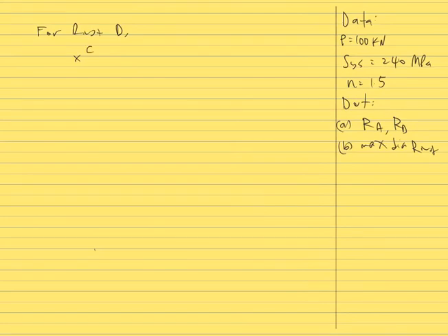So this is our centroid, and then this is our rivet D. So distance between centroid and rivet D is 90 mm RD. And then we have applied force acting on centroid, which is P is equal to 100 kN with an angle of 30 degree. And then at rivet D we have shear force acting opposite with the applied force with an angle of 30 degree.